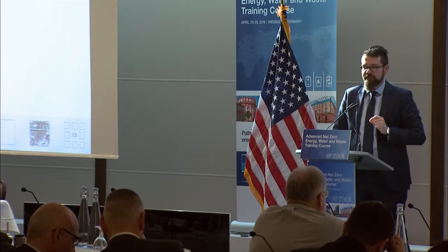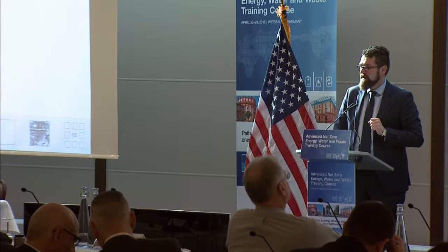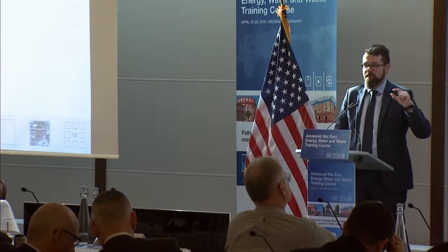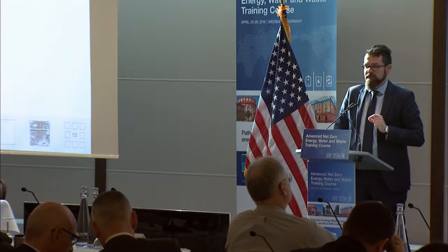So if we lay out the piping system and the generation equipment, we are going to design it for the total peak load or the assumed future total peak load. And this peak load is less than the sum of the single peak loads due to the load profile through the day and through the year. This reduces, beside the economy of scale Anders explained a little bit earlier, the capacities we need to install, and this comes up with a reduction of first cost when we're going to install it.